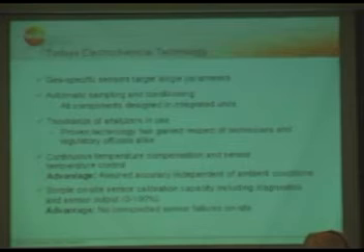But if you take care of this and you know the characteristics of such a sensor, you can do a temperature control and get rid of this characteristic. All of our analyzers are temperature controlled. We measure the temperature inside, depending on the sensor or within the sensor chamber, and then we do this compensation automatically. That means you don't have to worry if the ambient temperature increases or decreases. It will be compensated automatically.